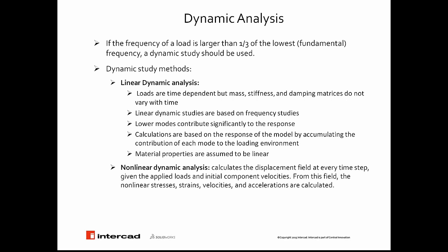And also one very important fact: when we're talking about linear, this linearity is considering the material. So if we have a nonlinear material and a dynamic loading, there is no other option than to move to nonlinear dynamic studies. We'll be calculating the displacement field as the primary unknown at every time step with the given or applied load. What we get is nonlinear stress, strain, velocity, and acceleration from such a study.